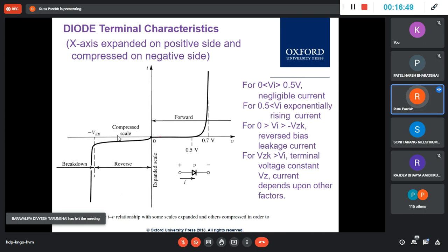So this is an expanded version, okay. IV curve is the same since the diode is the same, but because the two diodes are different, okay, and one you are giving a strong positive voltage. They are the same kind of diode but they are different diodes, okay. So what will happen is the one with the stronger voltage will start conducting with respect to time little bit earlier.